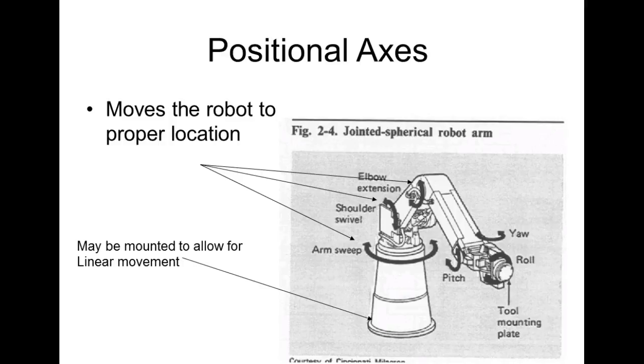So this is our advantage. Of course, we're very, very mobile with how we move, right? So that's two advantages. On ours, the orientation axes will be axis 4, 5, and 6, because notice when I move these, my arm itself is not changing position. The only thing I'm moving is my hand. When I move my elbow here, which would be axis 3, and when I move these, which would be axis 1 and 2, I'm moving my whole arm, right?